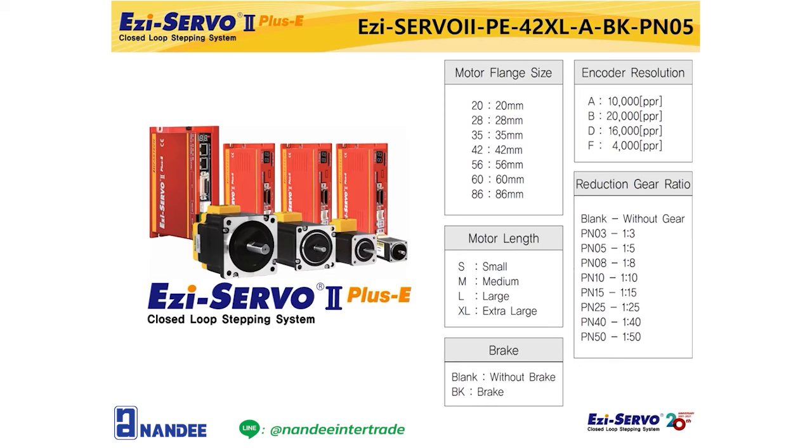In the example model name, PE means embedded controller with Ethernet network, 42 means 42 mm motor flange size, and XL means motor length. A means a product with 10,000 ppr encoder applied. BK means that a brake is attached to the motor, and PN05 means that a planetary gearbox is attached to the motor.